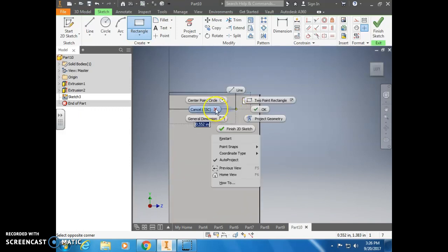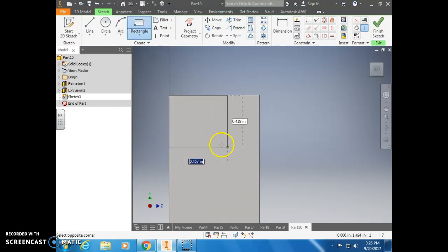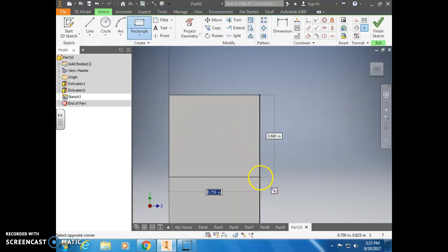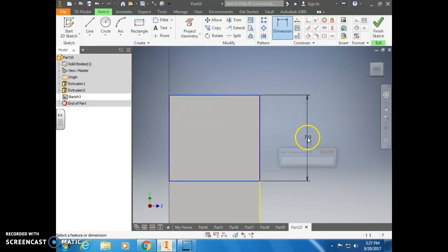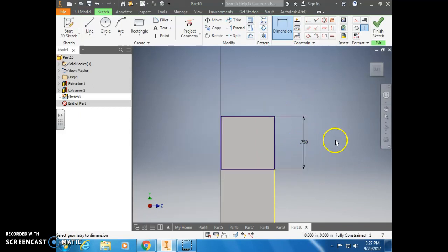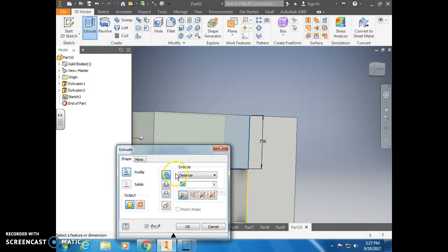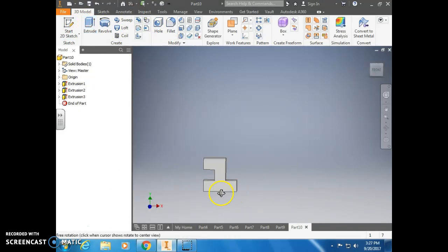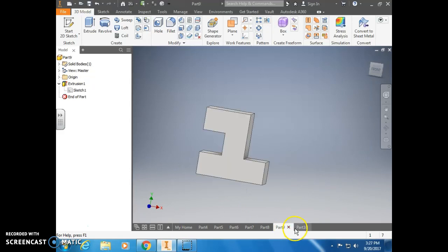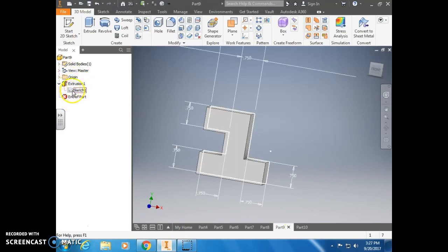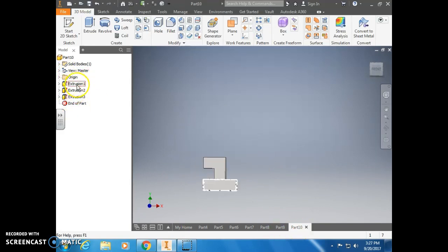That looks like I did a little bit above there. Not correct. A little bit below. Not correct. Take your time. I'm trying to do this really fast. Finish that. Extrude 0.75. And now I've got my object. So, whether you did it both of these objects are the same. This one I just did in 1 extrusion. This one took 3 extrusions, but they are the same object.